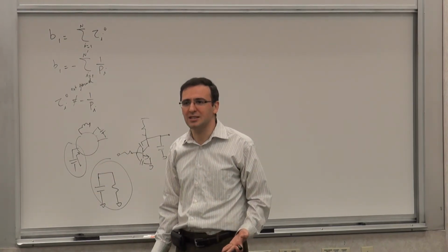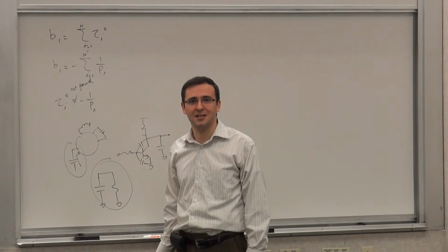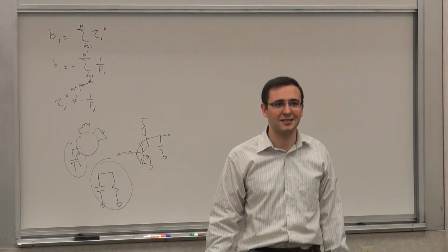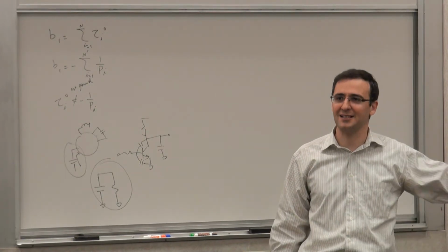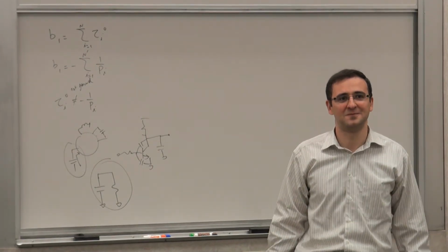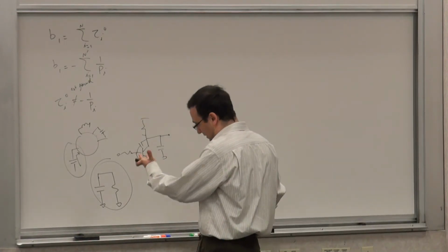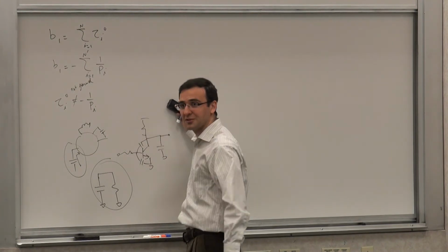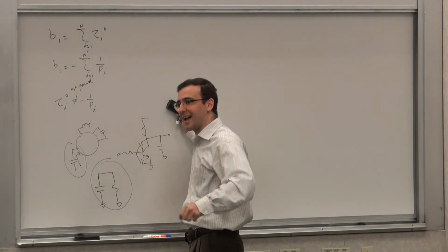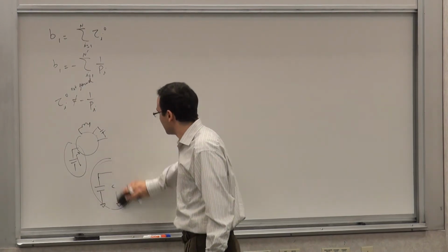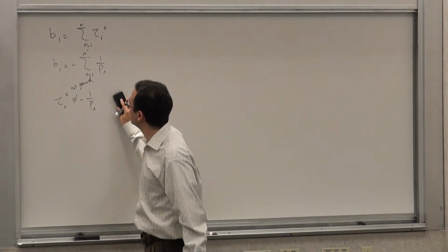You may say, wait a second, but this pole is not in the transfer function of the system. The interesting thing is that it also represented exactly the same as a zero in the transfer function that we calculate. It's exactly sitting on that pole. So it doesn't violate anything, it works out nicely. But it will give you both a zero and a pole in this transfer function that are exactly on top of each other. So irrelevant.